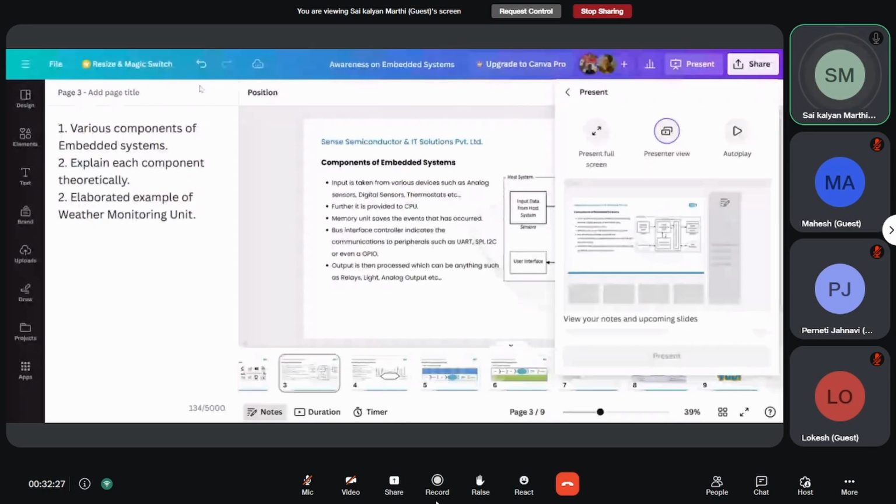So the software team will get, okay, you have one sensor communicating over I2C, one sensor communicating with the UART, and one sensor communicating with the SPI, and those data sheets will be given to the software team. Then the software team will analyze the resources, identify the resources which the controller has, and then they do the test plan as well.